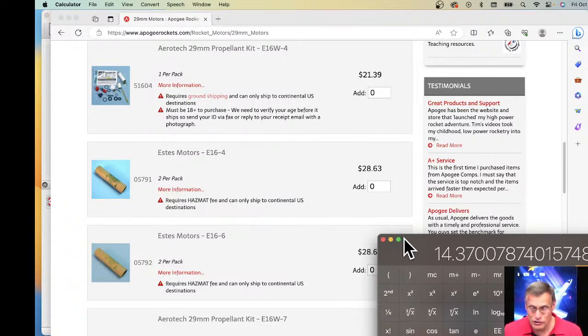If you're going to do that, I would put a thick layer of epoxy on the back bulkhead of the baffle to protect it. The epoxy is pretty flame resistant. You'll get sooty, but who cares? Nobody will see it.